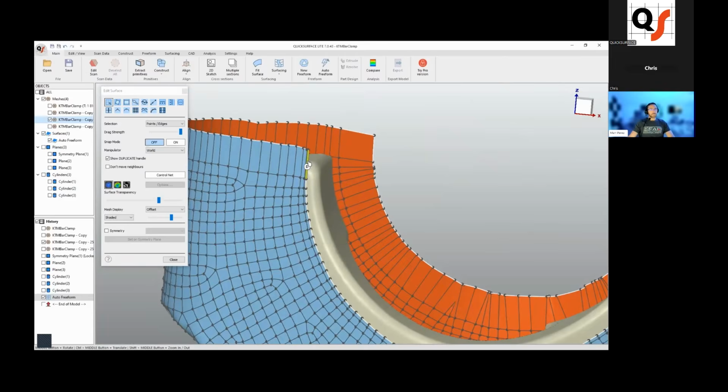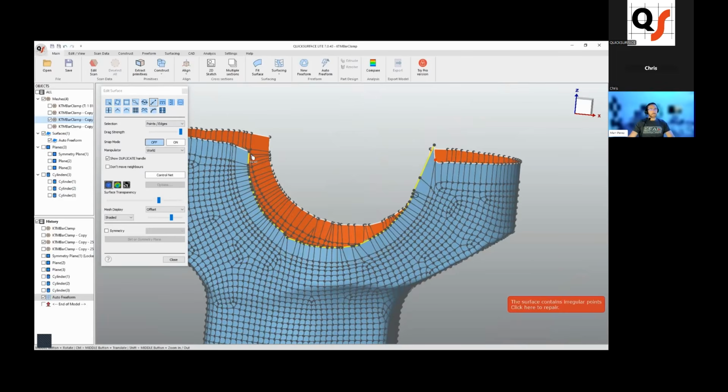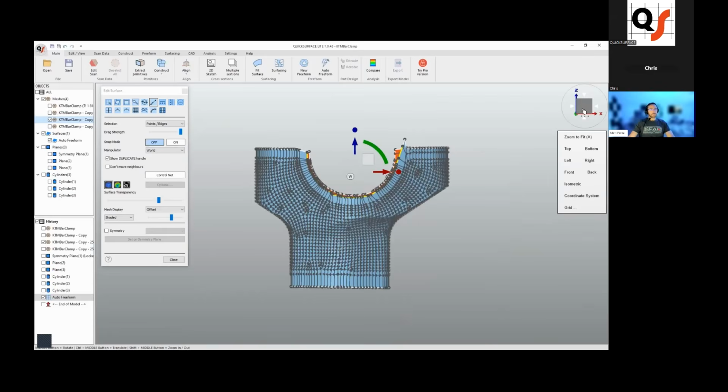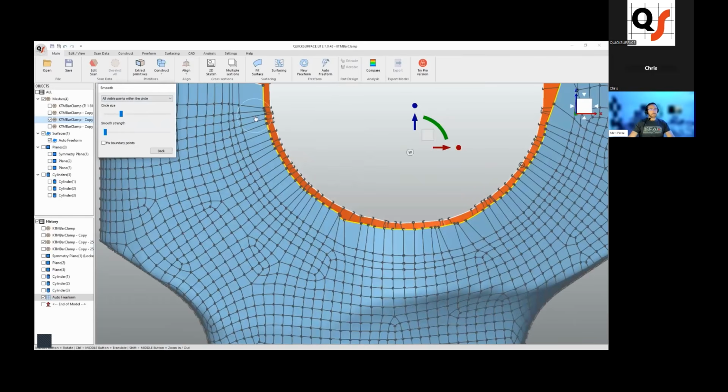And let's see if we can't, it really wants to go all the way around. So let's select here, Control and double click, go back to Extrapolate, and then pull this inward. It's causing problems. So again, we're going to have to deal with this, but let's go ahead and click that irregular point. And then the next step is to go to our smoothing brush. And anywhere where we see these start to bunch up, what I'm going to do is just kind of use that smoothing brush and get them to extend out a bit. So kind of get them to space out.